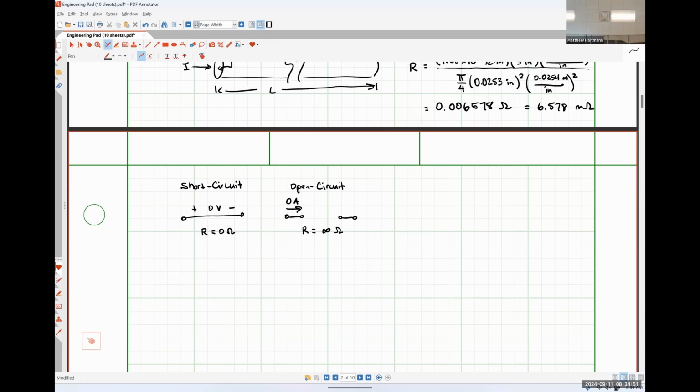So we know fundamentally that a wire has some amount of resistance. Realistically, we could have a very small voltage drop across what we would consider a short circuit in practice, right? Is there an analogous thing for open circuits? Absolutely. We can push current through an open circuit if the voltage is high enough to literally ionize the medium between the terminals of the open circuit.